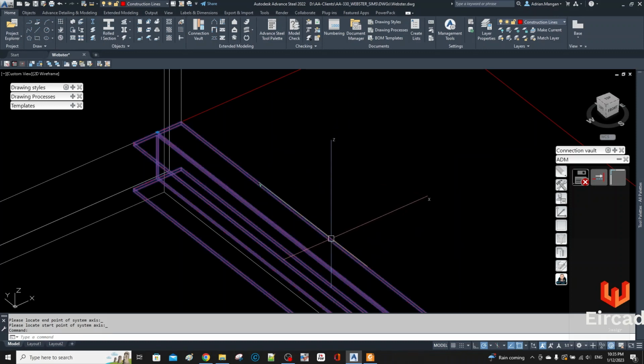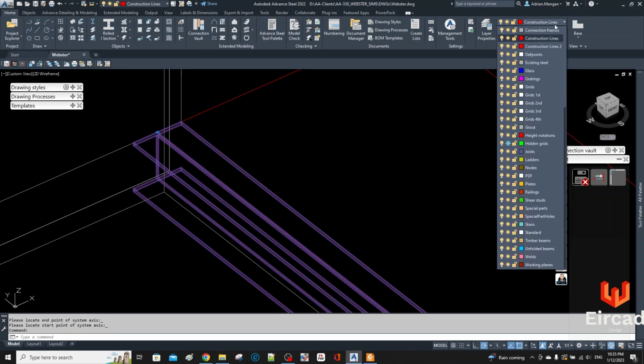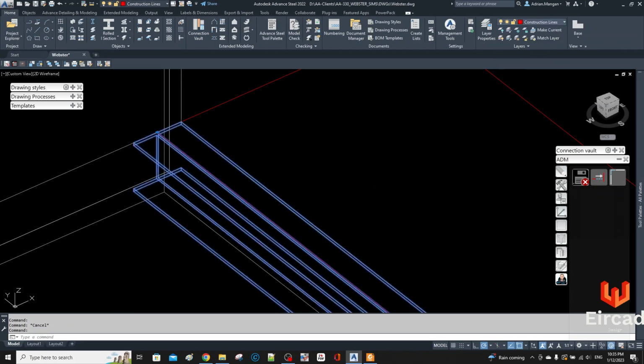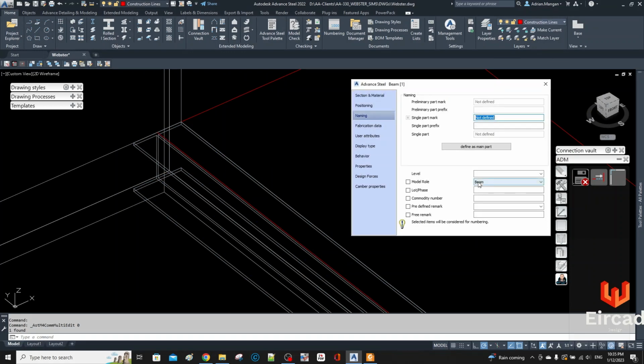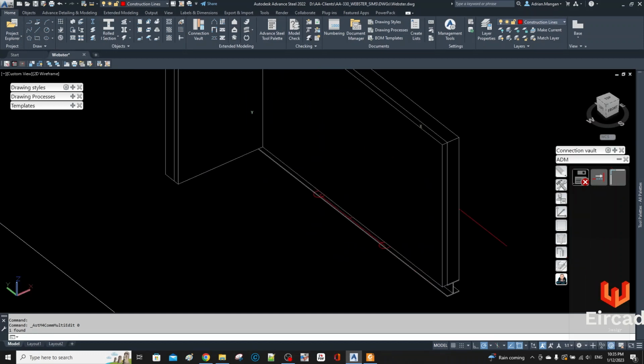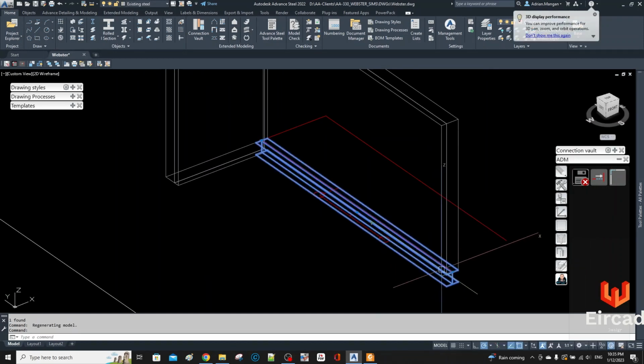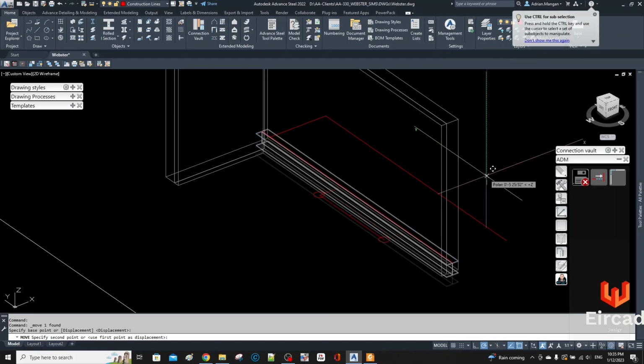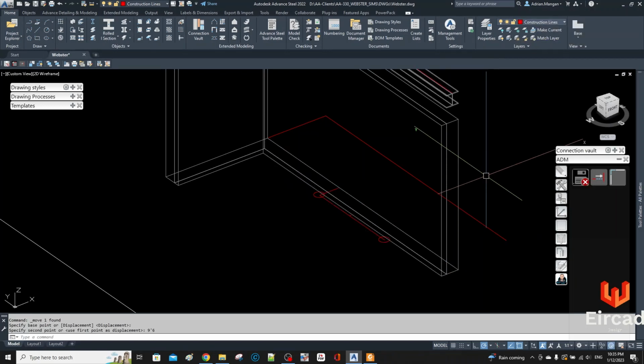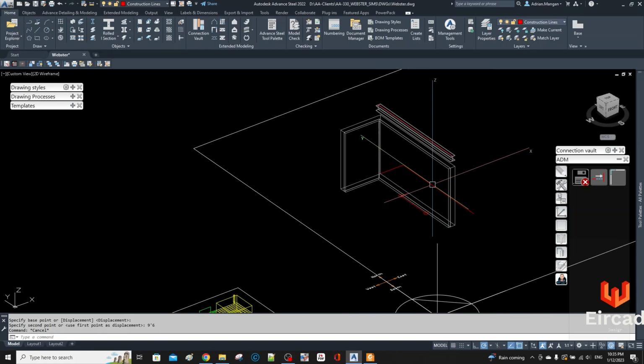Okay, now just select the beam. Actually I did make a mistake there, but it's fine. I'm going to go back in here and I want this to be existing, but now when I change it this way, the next one will still come in as a beam. Existing. Okay, so now that's my beam, and I wanted to put that at 9'6", right?